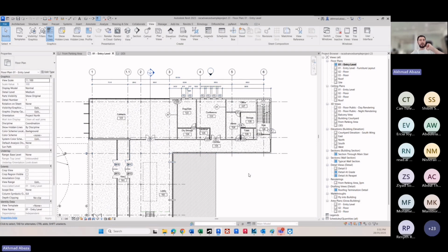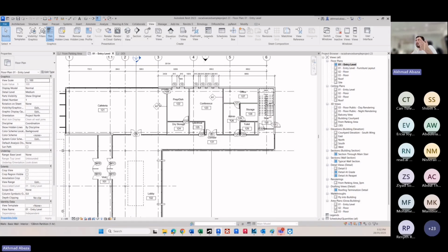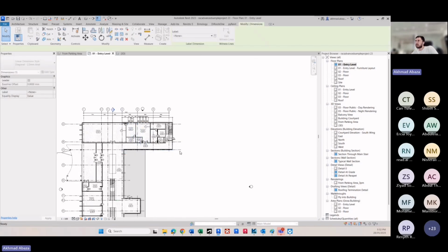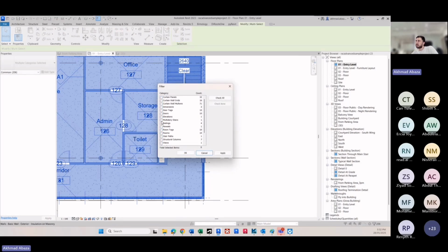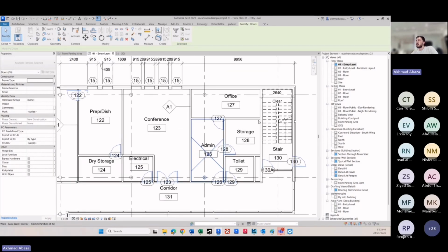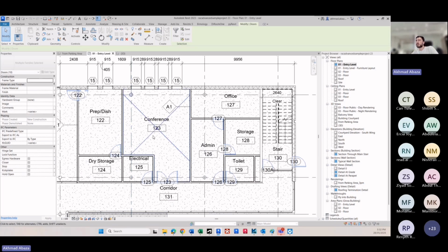Even if most or some of you started training previously and know most of this basic, sometimes repeating the information another time will make sure that the selection and navigation subject is closed. While working in Revit, you know that when I want to select these doors, I will just open a box like this, then filter, check none, doors. This will decrease the unnecessary time spent on doing manual things.